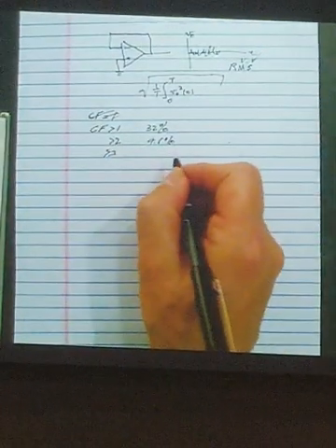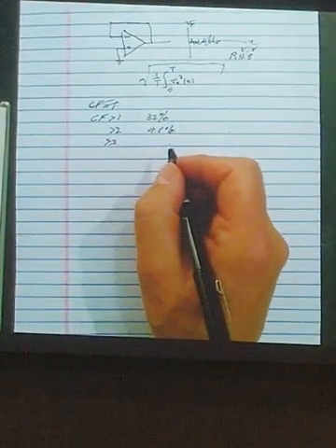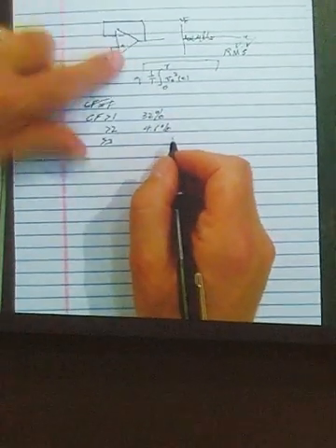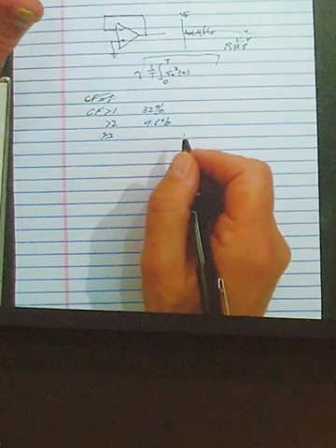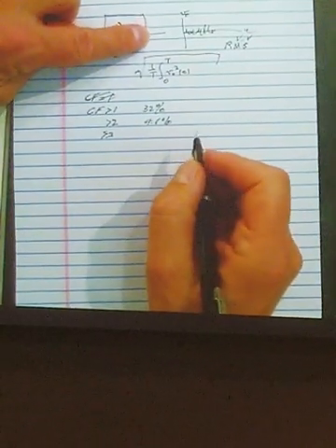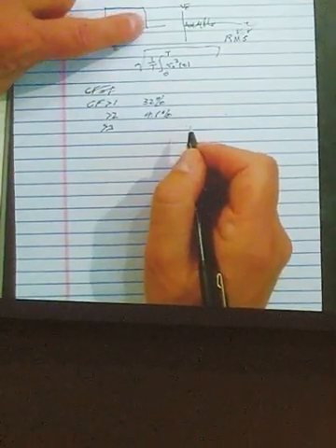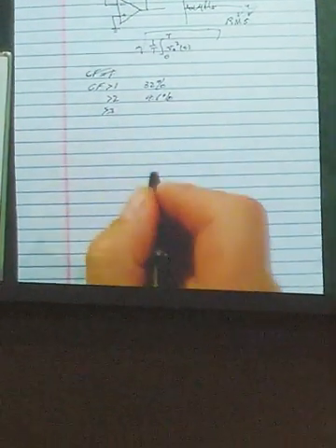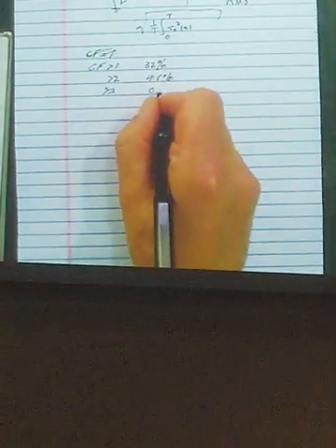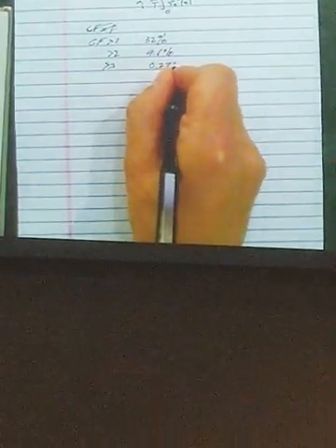Greater than 3. So again, if our op amp here has an output noise that is 1 millivolt RMS, really noisy op amp, how often is that output going to be above 3 millivolts? And the answer is 0.27%.